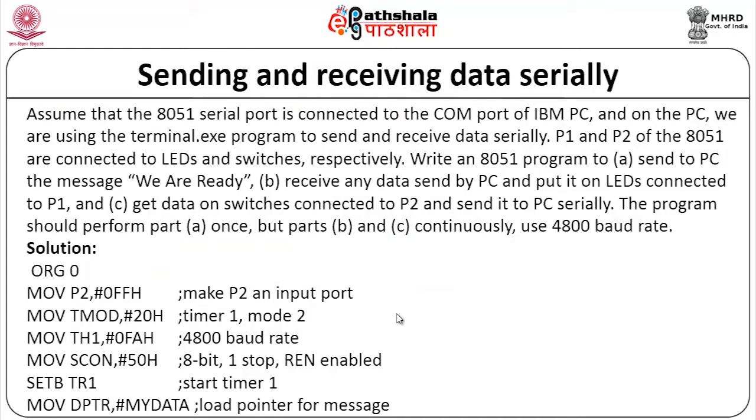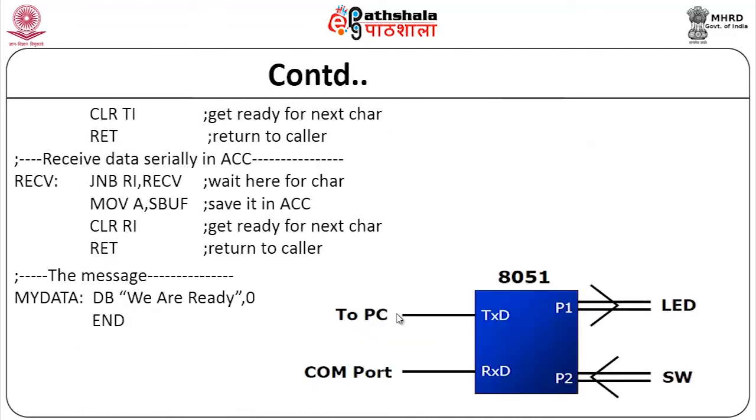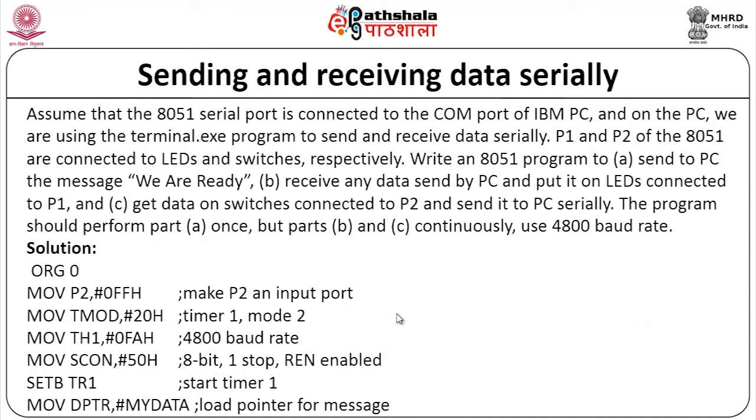This is the problem where the 8051 serial port is connected to a COM port of an IBM PC, and we are using a terminal program to send and receive data serially, where port 1 and port 2 of the 8051 are connected to LEDs and switches. You can see that P1 is connected to LEDs and P2 is connected to switches.